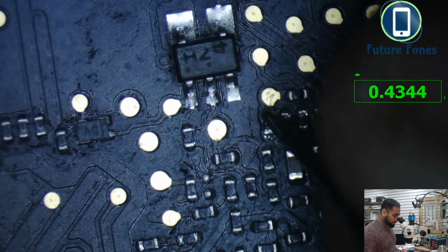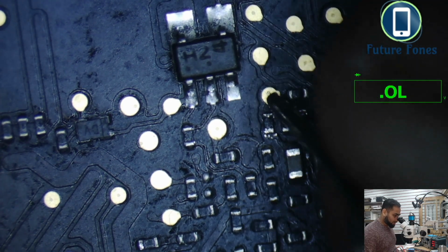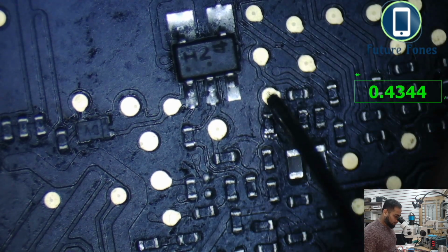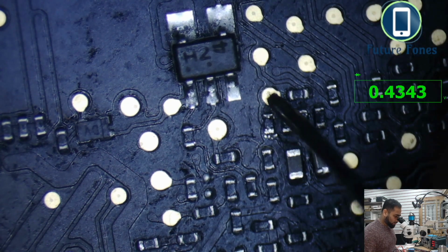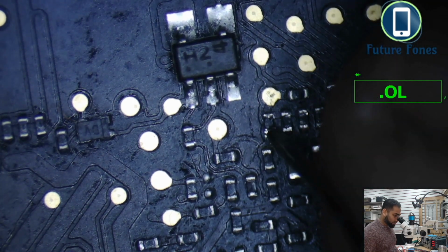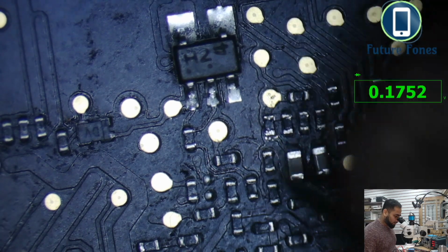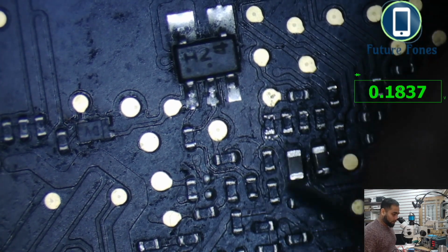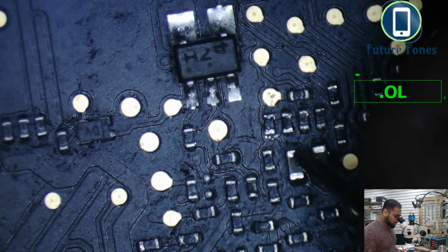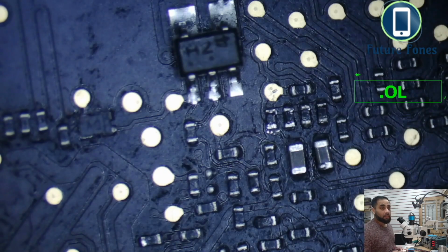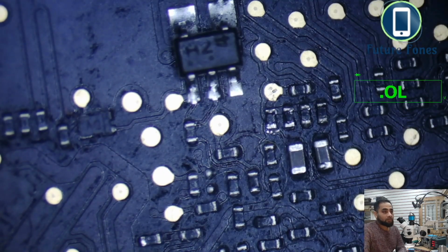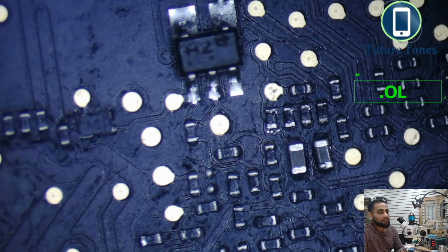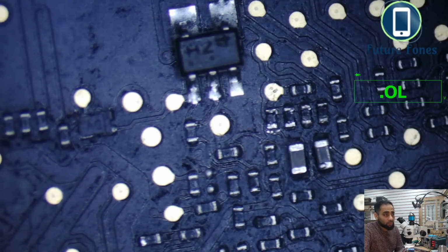I'm in the diode range at the moment, and it's a healthy diode mode value here, 0.433, but when it comes here it becomes 0.17, which I cannot doubt at the moment, because this RTC VCC connection at R1300 is going into the CPU, and anything that is going into the CPU has a low resistance.